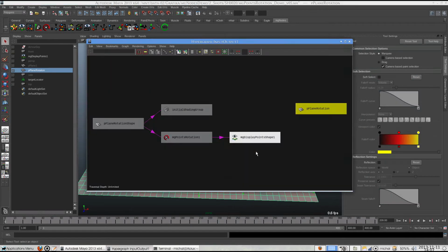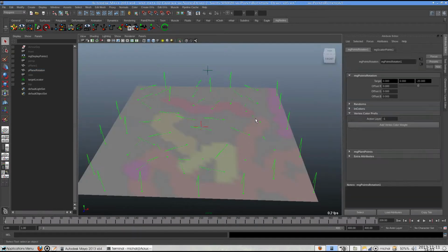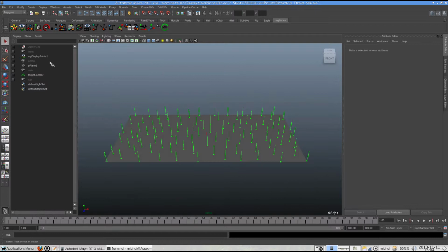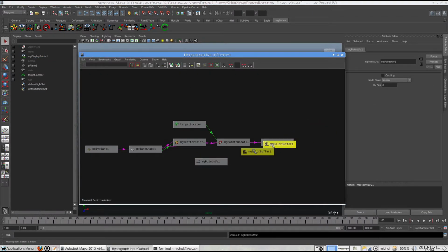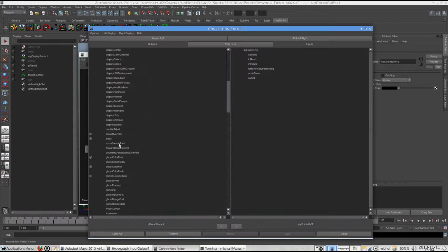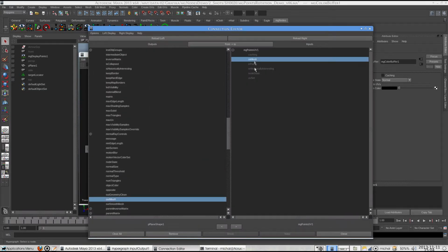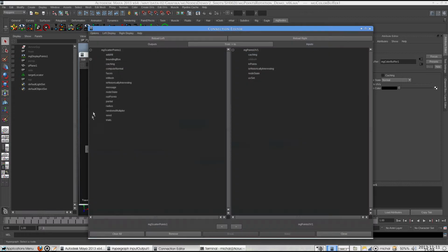Manage vertex color layers in mgPoints rotation node. Adjust weights to achieve desired result. Maya texture node can be utilized to define points rotation. Set up appropriate network using mgPoints UV, mgColorBuffer, and Maya texture. mgColorBuffer node performs serial calculation, so for big amount of points it can slow down playback.